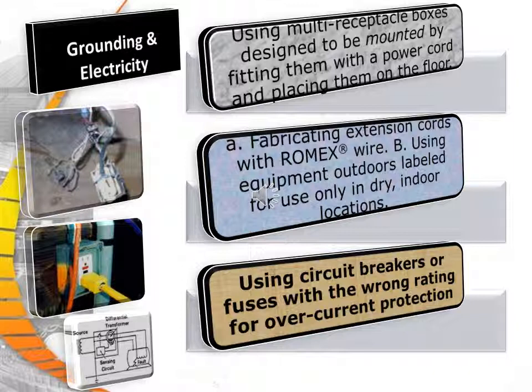Using multi-receptacle boxes not designed to be mounted by fitting them with power cords and placing them on the ground, fabricating extension cords with Romex wiring, using equipment outdoors labeled for use only in dry or indoor locations, and using circuit breakers or fuses with the wrong rating for overcurrent protection all present hazards.